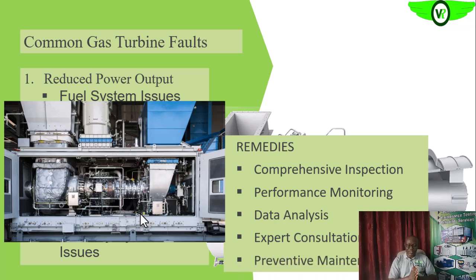Then our preventive maintenance schedule, as we said earlier, we do not want to miss it for anything. The normal routine inspection, change of filters, both fuel and air filter, the change of the oil, coolant, lubricants, and what have you. We want to maintain that normal PM schedule on the gas turbine, so all of this will help to maintain the efficiency of the gas turbine.